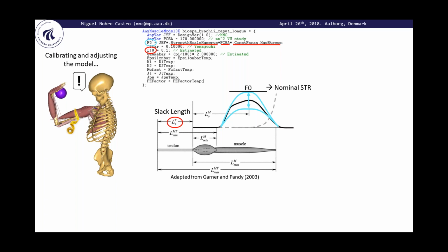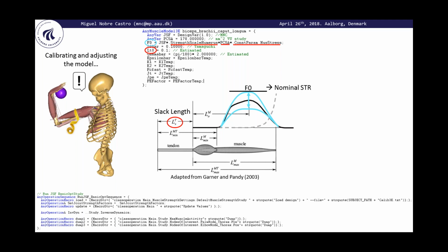And the optimal muscle fiber length was also predefined in the musculoskeletal modeling system. So it's very important, to perform this analysis, that you save the calibration values for these predefined variables, such as tendon slack length, on your models, and then every time you perform an inverse dynamic analysis, you just need to read in these subject-specific values. Otherwise, the computation takes much longer because you need to calibrate the model each time, and that's not what we're aiming for here. We should save some time.